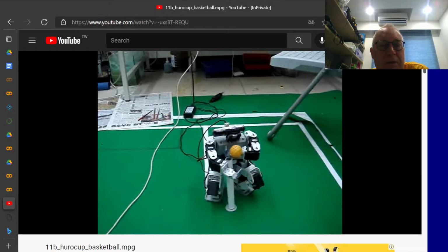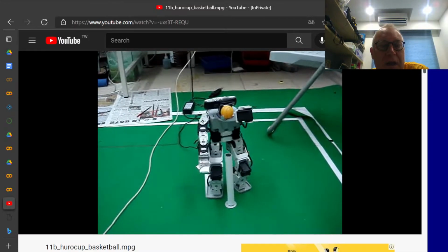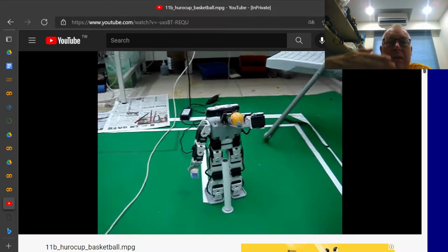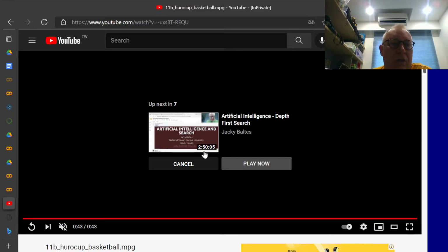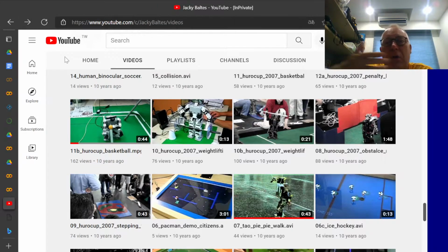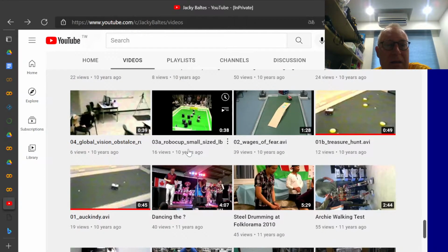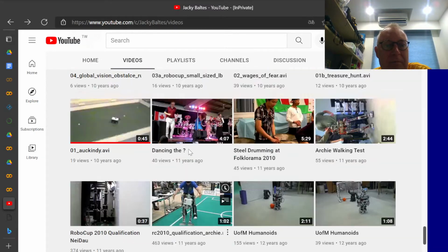This needs to be very precise, so we had to implement a visual servoing approach where we look in the camera where the ball is and where the hand is to make sure that they're aligned. And then we had to move the ball out of the way of the camera, otherwise the robot was not able to see the rest of the playing environment anymore.